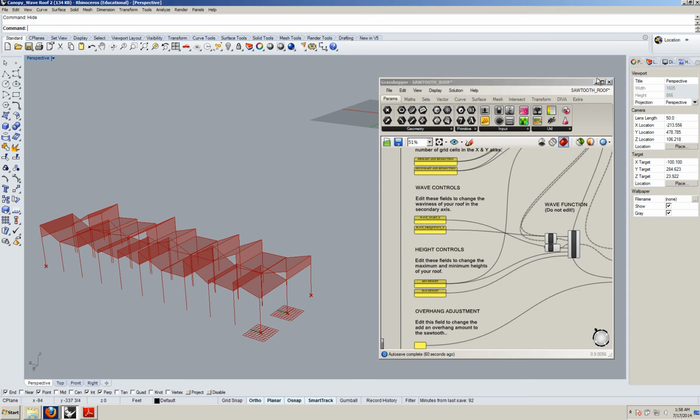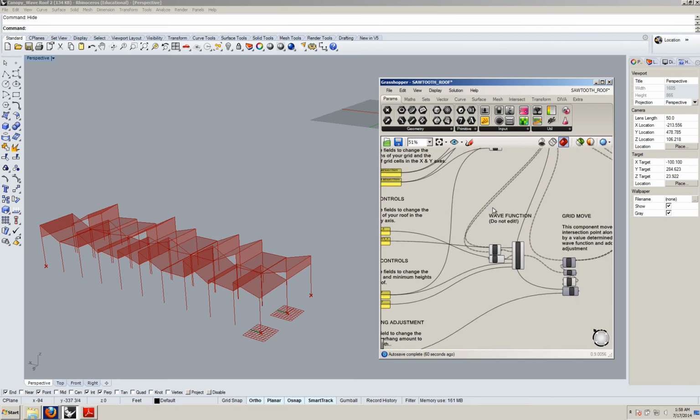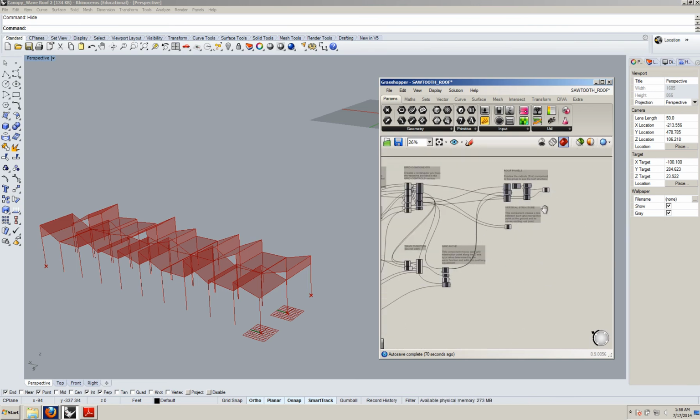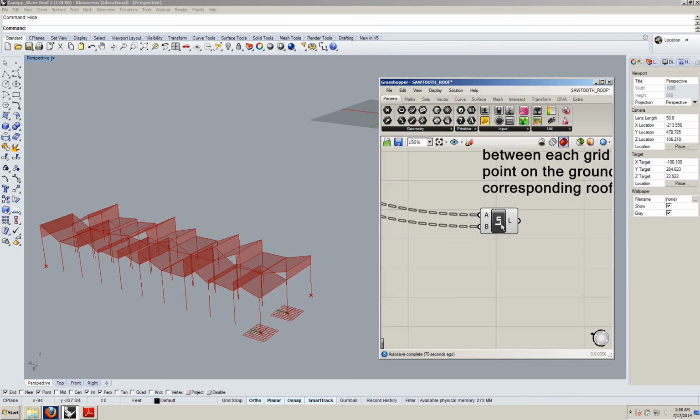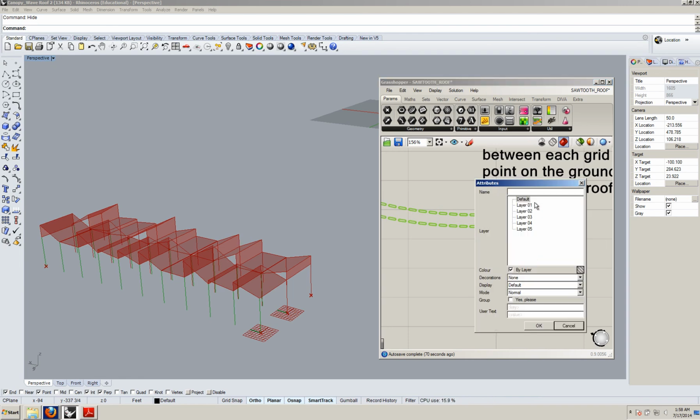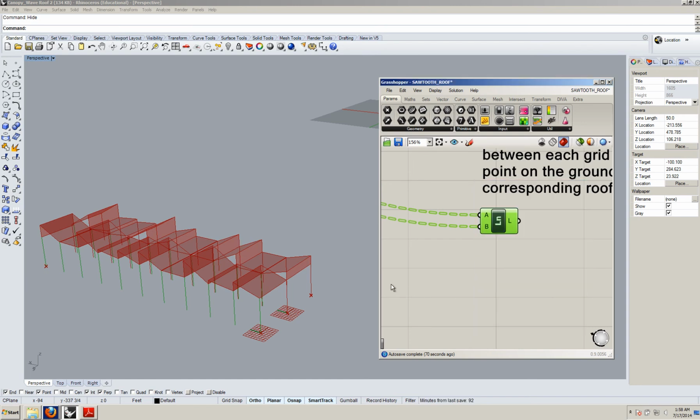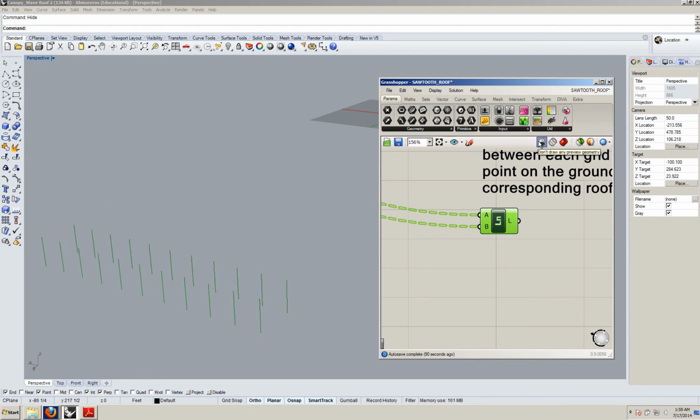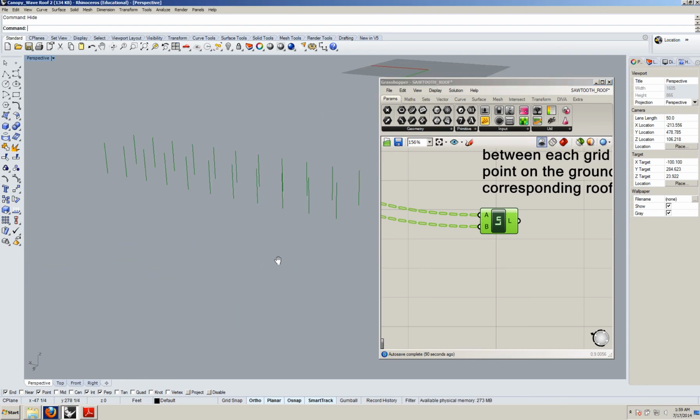I did want to show you one quick thing in Rhino that will help you with some of this, which is your lines once you bake them into Rhino. Put them on layer 4 this time. And I'm going to unpreview my Grasshopper geometry. Remember that happens up here, so I want it to not be previewed. So I'm just looking at the lines at this point.